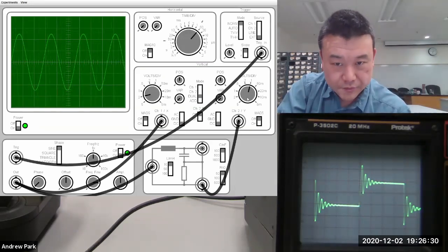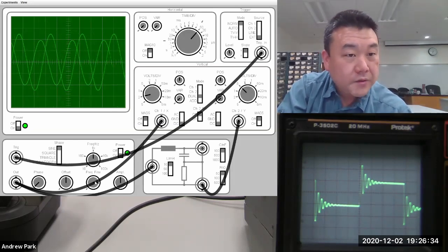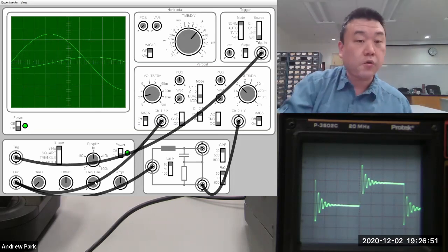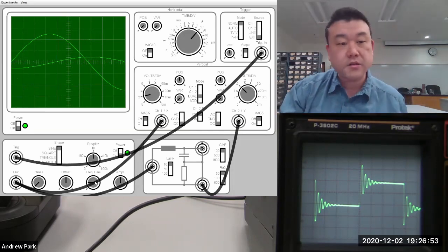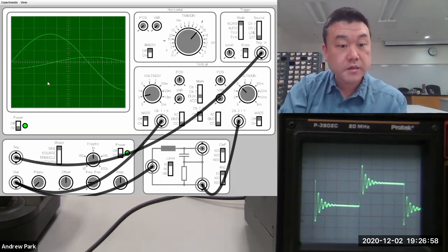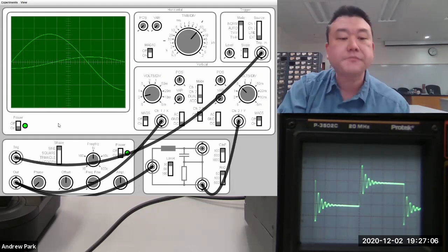Yeah, and I need to change this more. Okay. Yeah, so I think I passed the resonance there. So this is what's called the RLC circuit resonance. The amount of current that's flowing through the circuit is frequency dependent. So right now I'm driving the circuit off resonance, so there's some amount of current flowing through, not that much.